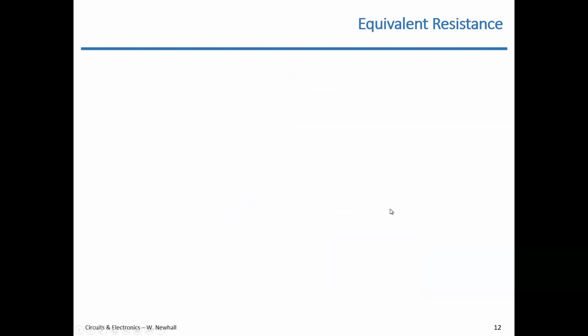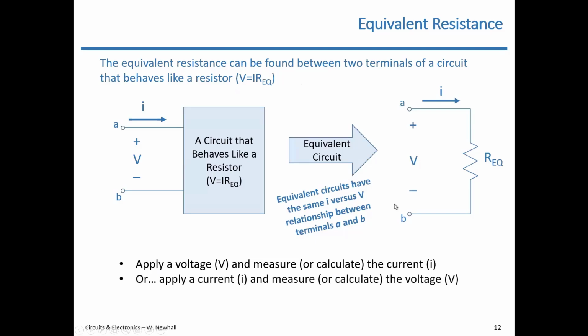Let's see. The next chat question was, would relying on more resistors also be used to help prevent overloading the resistor and breaking it? Yeah. By overloading, I would consider that to be when you exceed its ratings. Resistors have a maximum power that they can dissipate, and a maximum voltage that they can handle, from which, by Ohm's law, you can figure out the current. For smaller resistor values it usually comes down to how much power they can dissipate. For very large resistor values, you might get some voltage breakdown. But the answer is yes.